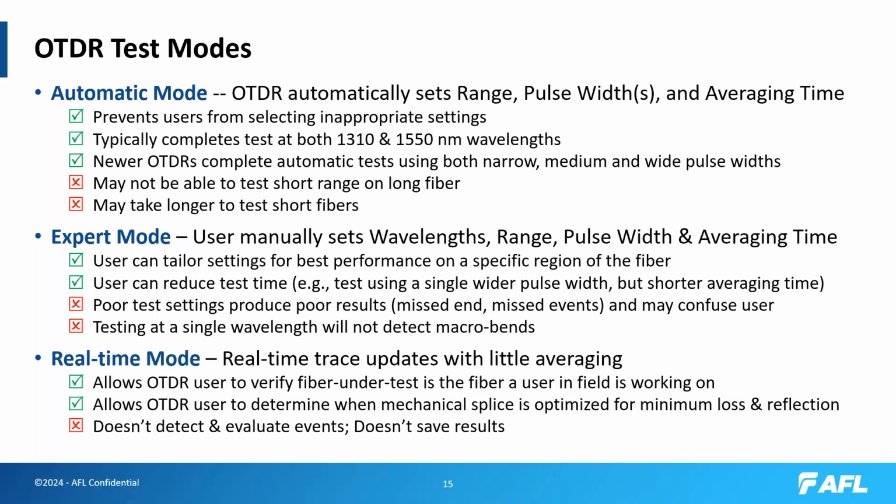Lastly, real-time mode. So real-time trace updates with little averaging. So your averaging time might be a second, 2 seconds, or less. This allows the OTDR user to verify that the fiber under test is the fiber a user out in the field is actually working on.